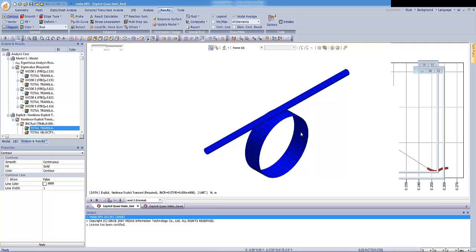So now let's take a look at the second example we prepared for you. I want to show you a quasi-static example using an explicit code with some practical advice. As you know, we can use explicit code to perform metal forming simulations like rolling, drawing, or sheet metal forming. And as you probably expect, at first glance, the implicit solver is the better choice.